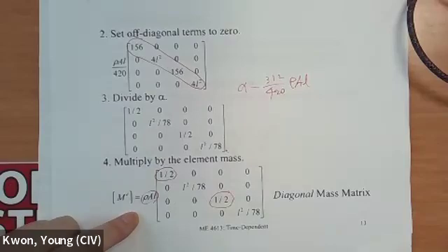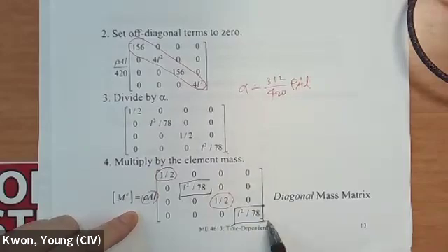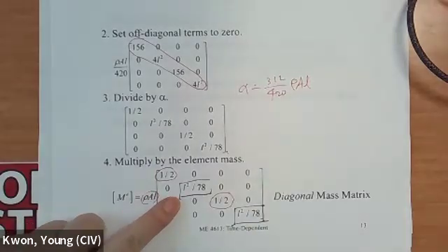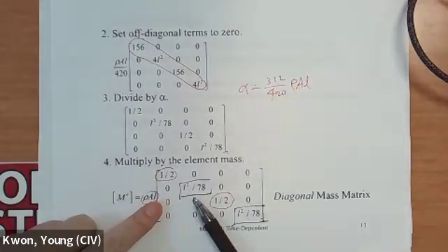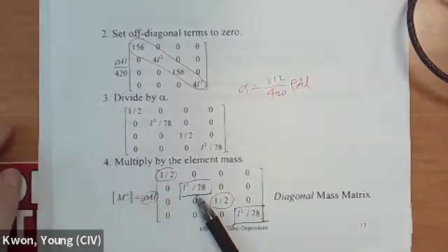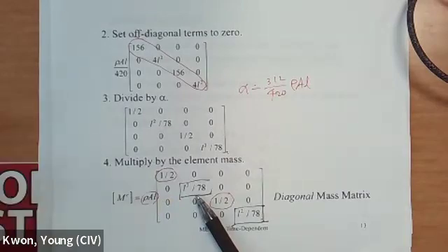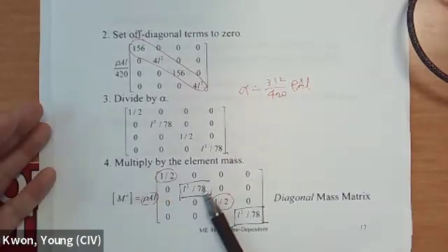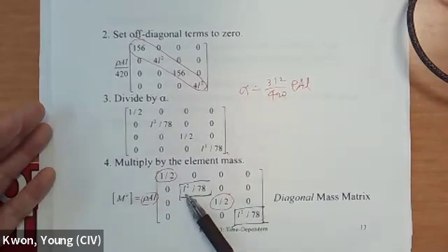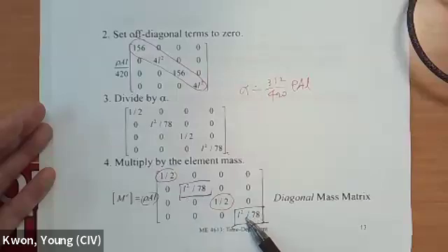And this number, the rotational mass here, really doesn't matter. I mean, it is non-zero, so that's good. But this value is very trivial. Eventually, as L becomes small, this goes to 0. So the impact is going to be small, but at least the diagonal mass matrix is invertible because it's going to be non-zero. That's the only purpose.